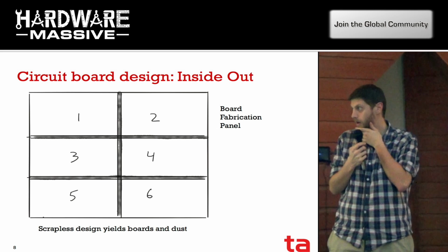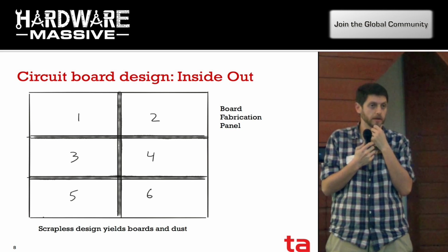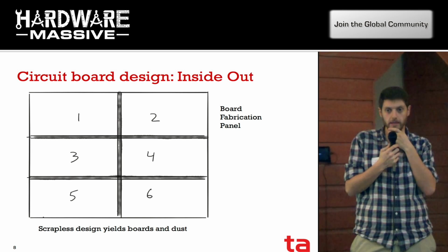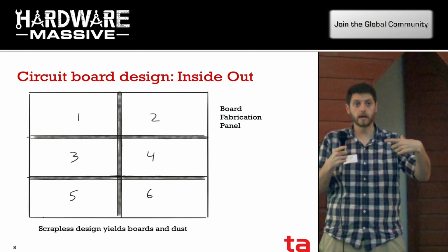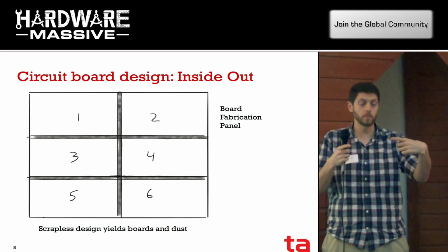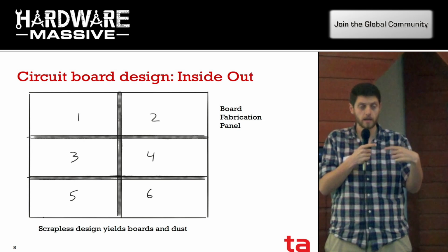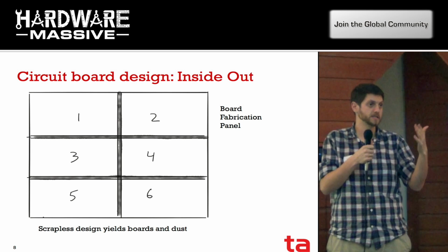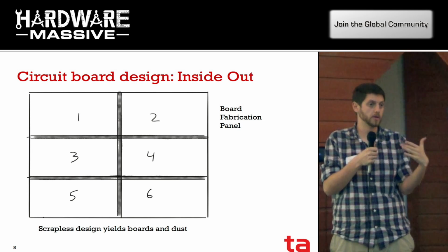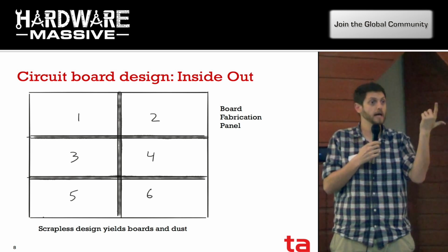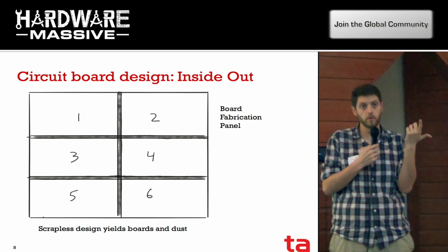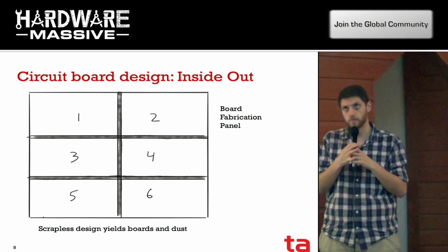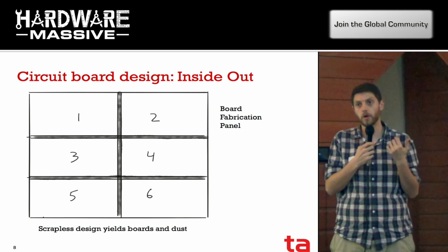Another way is more of an inside-out direction. One of the things to really appreciate about the electronics manufacturing process is the extent to which many of the fabricators involved with manufacturing circuit boards are really built around these 16 by 22 inch panels. All the equipment, process, and tooling is set up to support those types of panels. That implies some thoughts around how to design your board such that it supports those processes well.